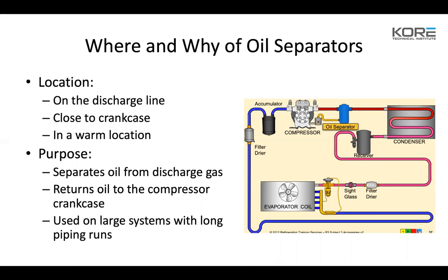I've had many situations on the Hussmann Super Plus racks where the machine room is open to the outside. Even though it's inside, it gets really cold there. Therefore, the separator gets cold, and then it starts bringing liquid through the oil separator into the compressors and knocks the compressors out. I've blown a couple head gaskets on some systems in that situation. So just make sure that your oil separator is nice and warm.